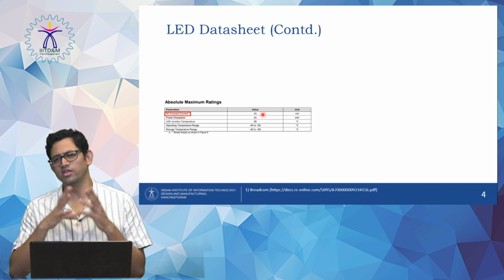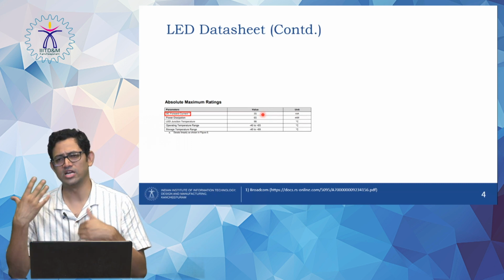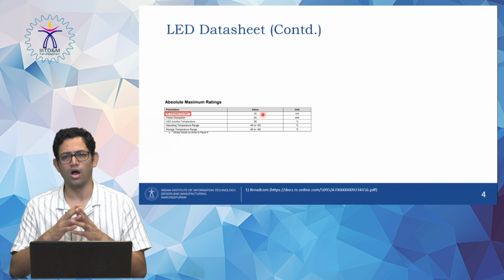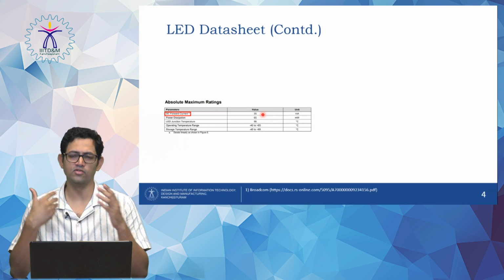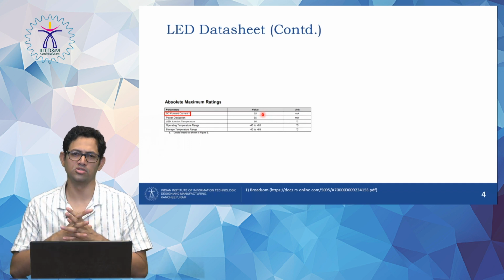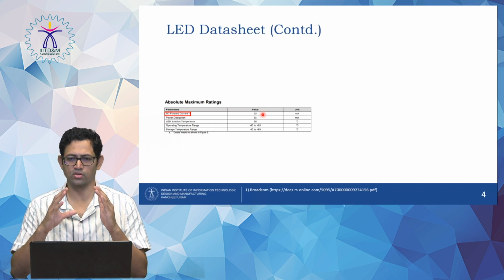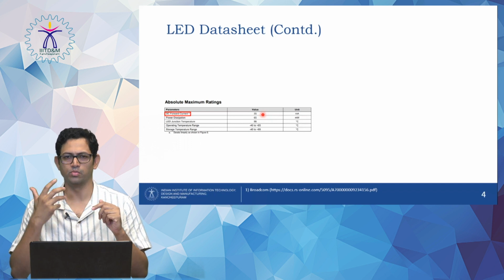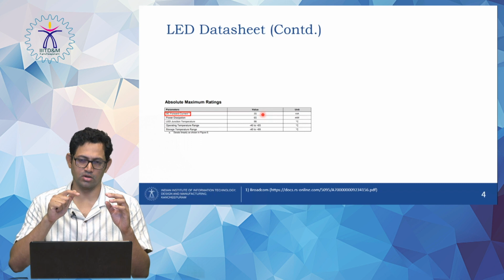And whether it is lasers or light emitting diodes, as you will see, the most important thing is the current. How are you giving the current to your optoelectronic device? That is one of the most important things that you have to make sure you are doing correctly. Otherwise, the voltage doesn't matter much compared to how much current you are driving.